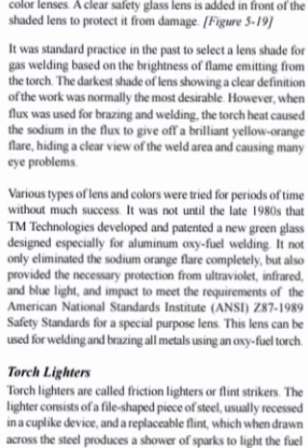It was standard practice in the past to select a lens shade for gas welding based on the brightness of flame emitting from the torch. The darkest shade of lens showing a clear definition of the work was normally the most desirable. However, when flux was used for brazing and welding, the torch heat caused the sodium in the flux to give off a brilliant yellow-orange flare, hiding a clear view of the weld area and causing many eye problems.